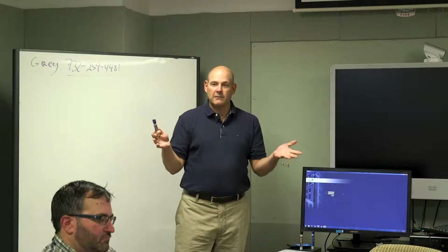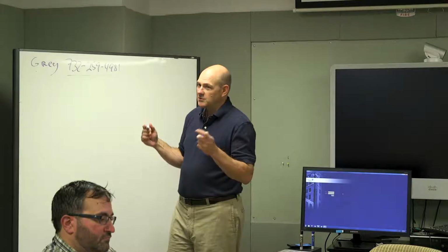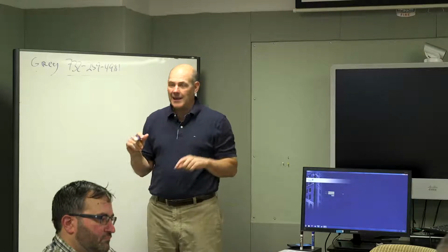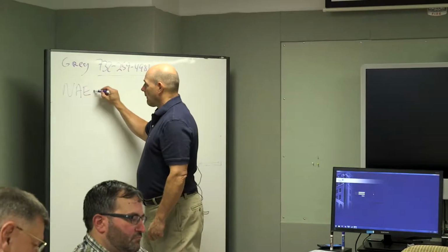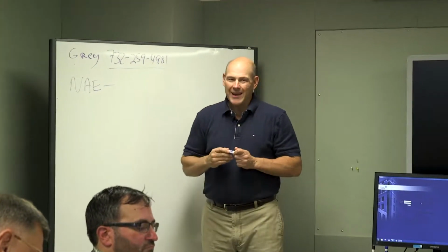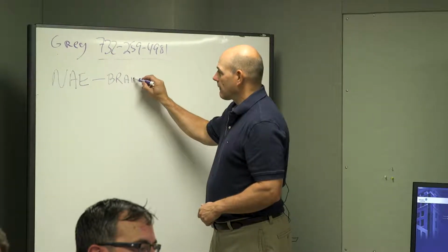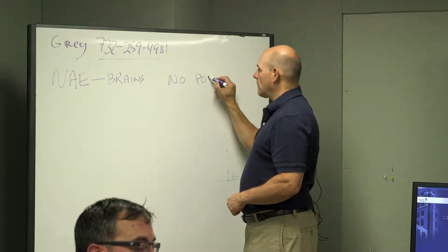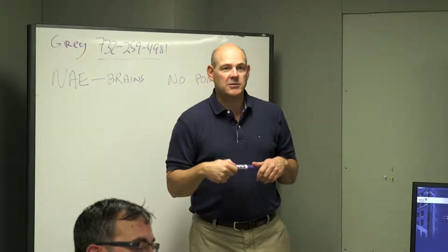All right, first thing I want to cover is what the Metasys system is in the field. So what we have is a couple of controllers. One is like the mother that has all the software in it. It's called an NAE. All right? That NAE has brains. It's all brains and holds software. And there are no points, no physical hardwires to it other than communication and power. So you need to know that.